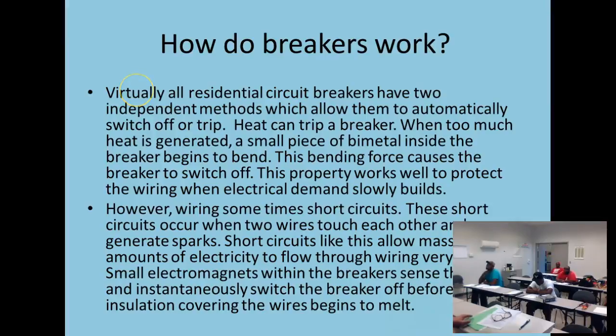Let's take a look at the breaker first. When we're talking about troubleshooting in here, you may have a problem with the breaker. We got one right outside that's on the air handler. Usually they give us these whenever you install a heater kit. If it's over 10 kW, they want either fuses, which they don't use much anymore, or a breaker. Now, breakers replace fuses because there are two safeties in a breaker. There's two methods, okay? I'm going to read y'all this.